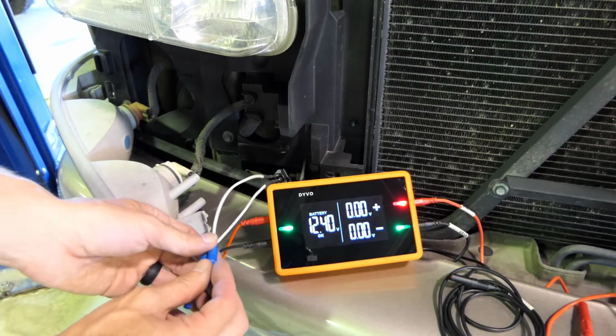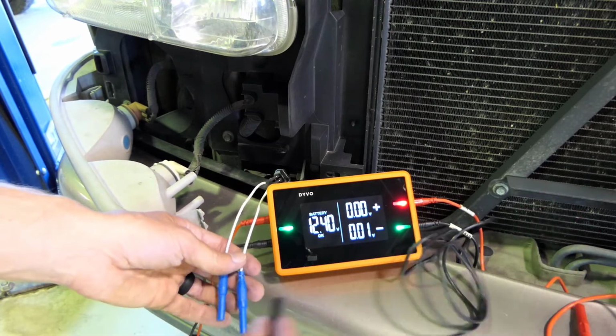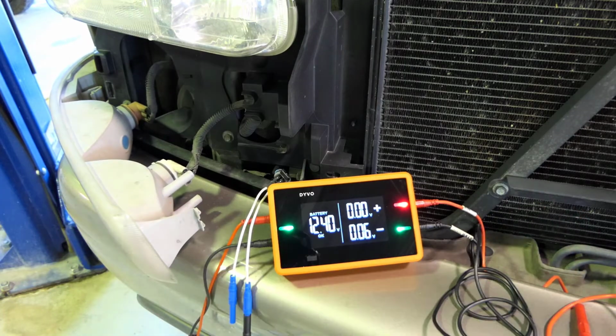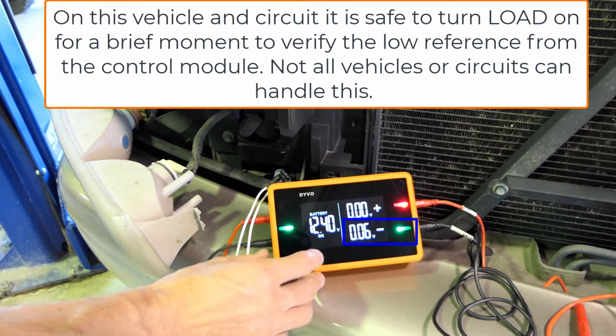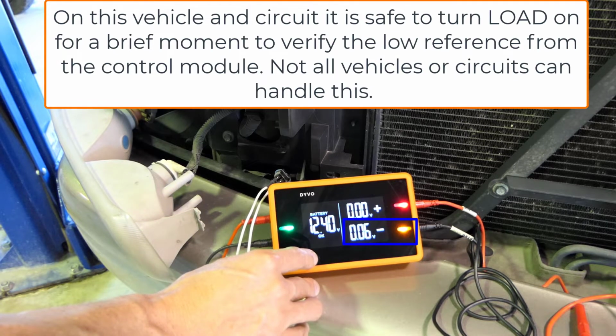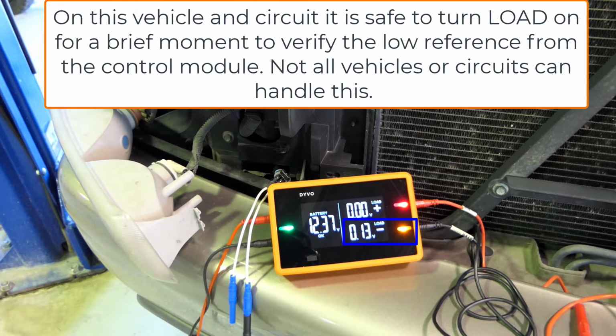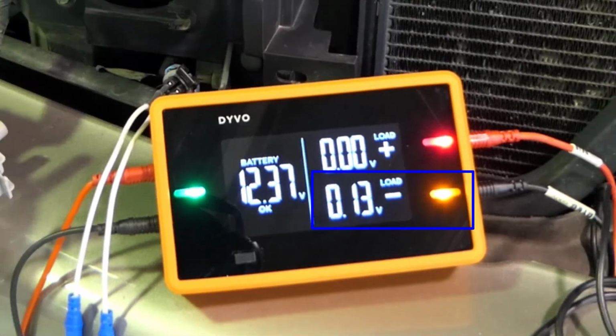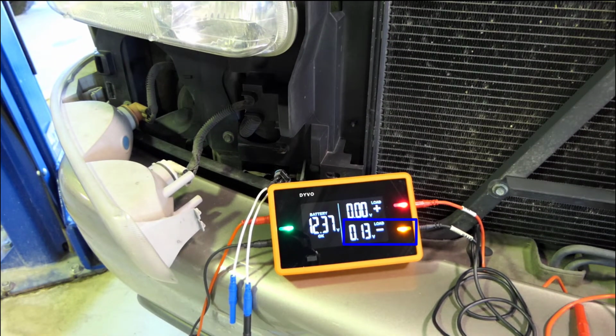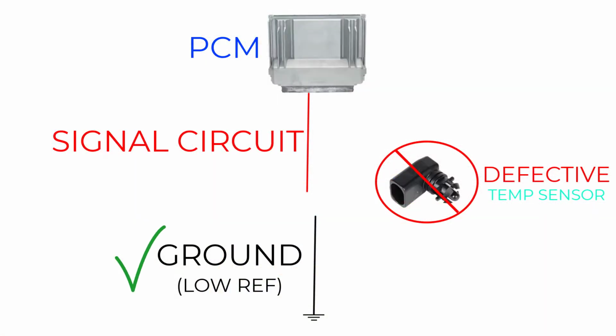Let's go back to the ground. I'm going to use the black test lead and connect it to my ground circuit. Remember that we're not in load mode, so we're not actually loading that ground circuit down. We do want to apply a little bit of a load to it, so I'm going to push and hold the mode button down. We're going to load that circuit down, and now we can see that it changed to 0.13 volts. We get a yellow LED, which simply indicates that we have some voltage loss on that circuit, but we can see by this value, 0.13 volts, perfectly acceptable voltage loss on that ground side, so I'm not concerned about that. So I know the ground to this is good.